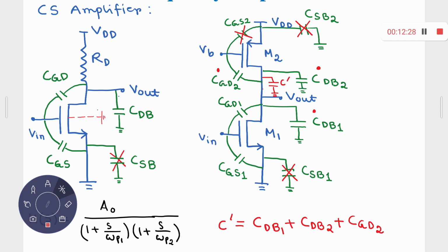Right? Okay. So that was the scenario for a common source amplifier with a simple resistive load RD. Now you can also realize this by virtue of some current source load. That means this RD is replaced by some current source device, and that is nothing but a PMOS here, so that you can simply neglect the corresponding body effect. Right? So now for M1, you have once again these 4 capacitors, CGS1, CGD1, CDB1 and CSB1.